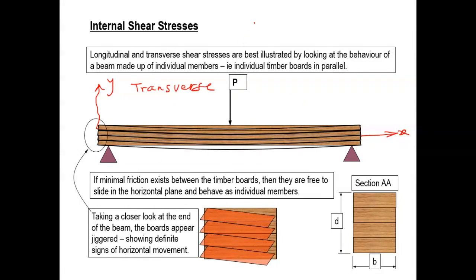So remember I told you that after the bending, there are two stresses developed here. Normal stresses, that was the flexural formula. We discussed that last week. It not only depends on x, it also depends on y. So in other words, yesterday we were trying to find x star, y star. What are x star, y star?